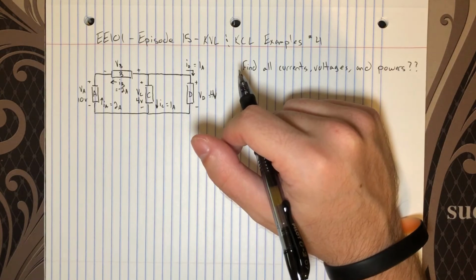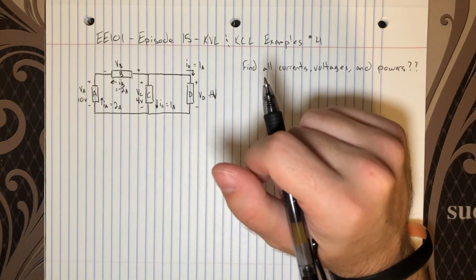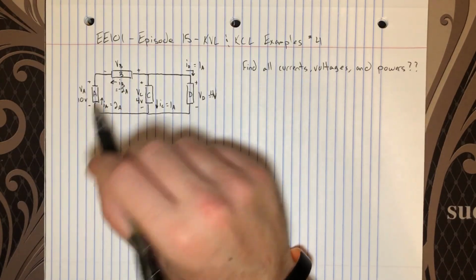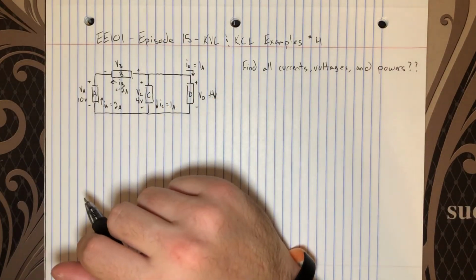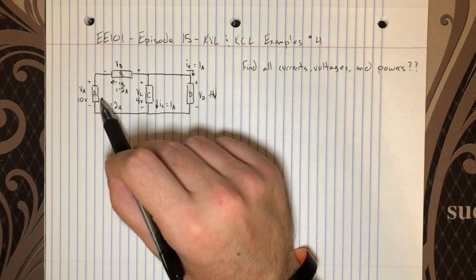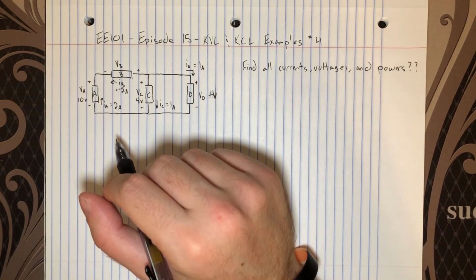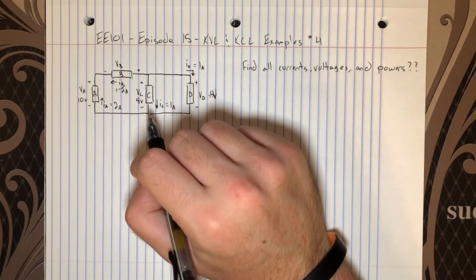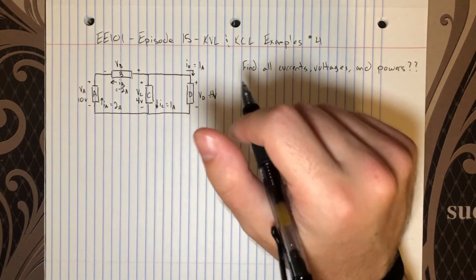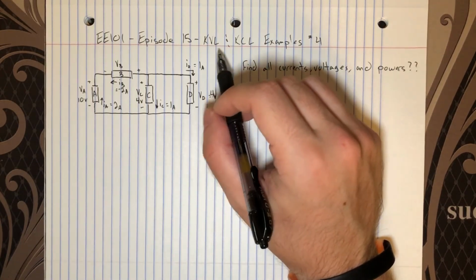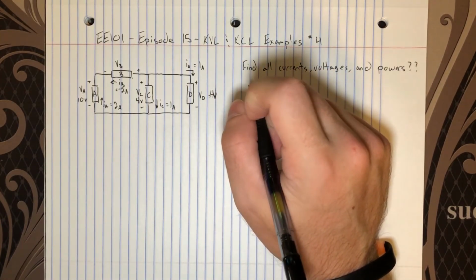Now, there's one piece of information we still don't have, and that's the voltage on B, VB. And in this case, we are going to do a KVL. There are two ways we could solve this, but I do want to step through an actual KVL because I feel like I haven't done one of these explicitly in an example yet.